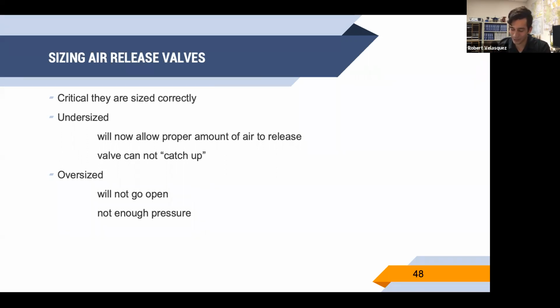That's really common. With air release valves, you want to look for the right size orifice. One of the things we've run into is when you don't have the right size orifice available, we'll see a lot of air popping out. So we work to make sure to get the right size orifice on there. And that's why sometimes the combination air valves work the best, because you can get that air release valve size exactly how you need it, and it's not over or undersized.